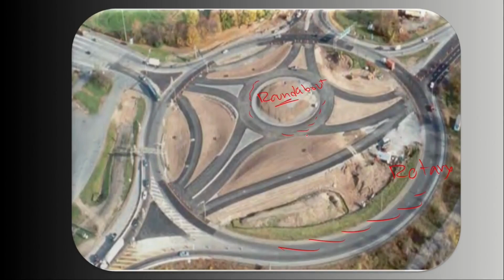a small roundabout. It's not the subject of this video to compare roundabouts with other conventional types of intersection, but since roundabouts control the speed by their geometry, no matter if it's peak volume hours or low volume hours, they're generally safer than other types of at-grade intersections like signalized intersections, where the traffic signal goes off during the low volume hours.